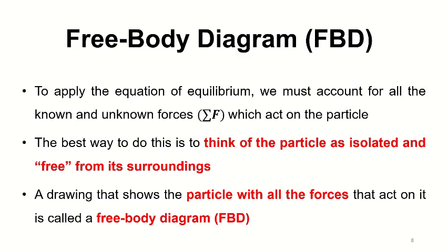So we must account for all the known and unknown forces acting on the particle. The best way to do this is to think of the particle as isolated, or free from its surroundings. We say we remove all the supports that the particle has and we isolate the particle from the surroundings.